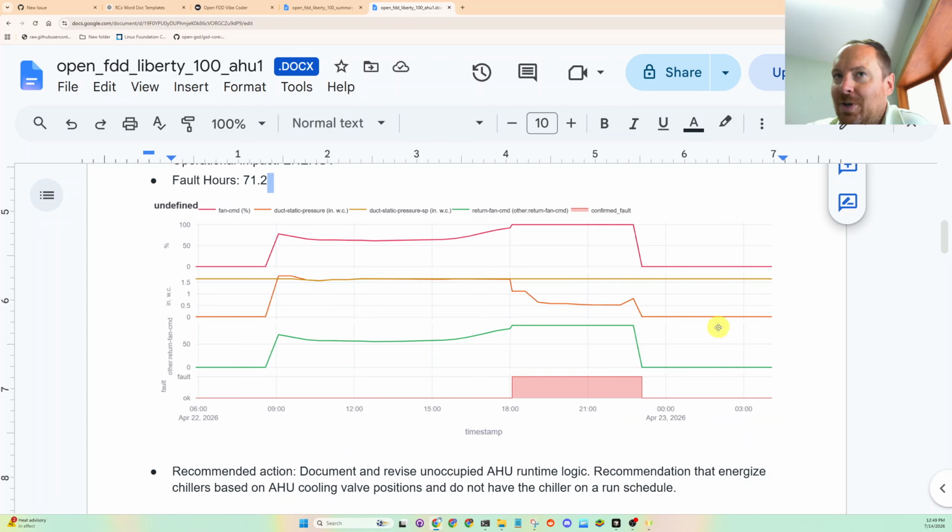So the air handling unit keeps going, and then all my cooling has gone away, and all of the VAVs are asking for cooling, but they can't get it. So air dampers open up, duct pressure goes down, and pretty soon you're blowing around a lot of air in the building for hours at a time, wasting a lot of energy.